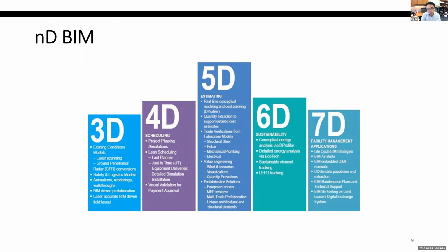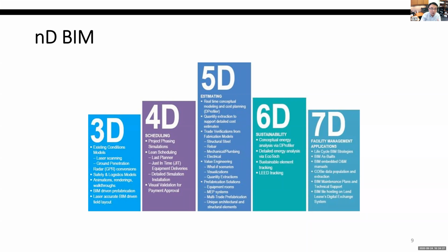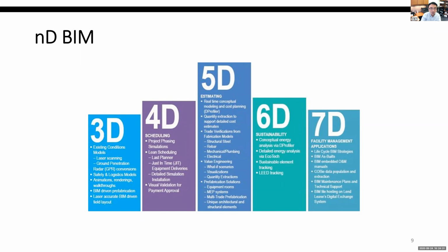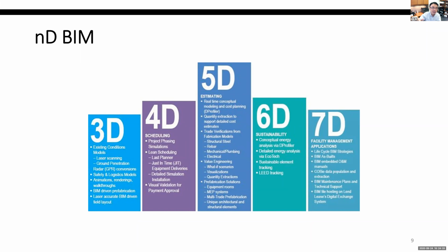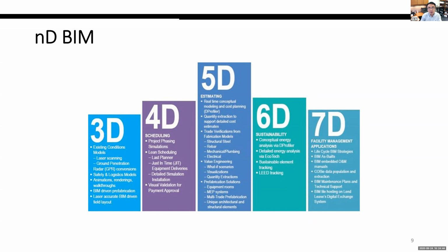5D can be used to run cost estimating. So I showed you guys a very quick demo, and we have this BIM model. We have the unit price built in. So just click one button, and I have a spreadsheet with all the quantity takeoff, as well as the total price for the project. That's 5D. A 6D application can be running the LEED evaluation.